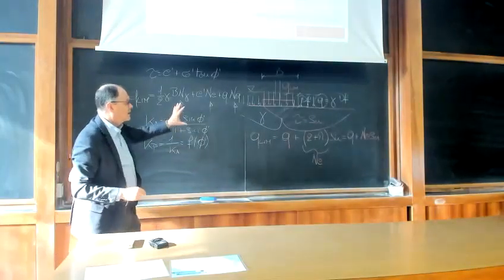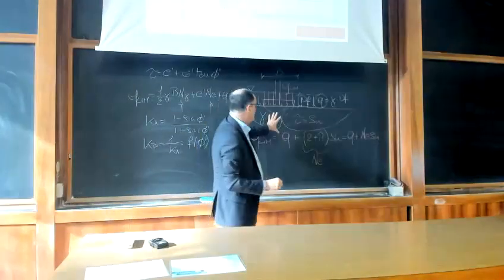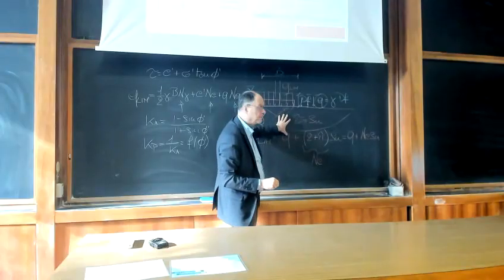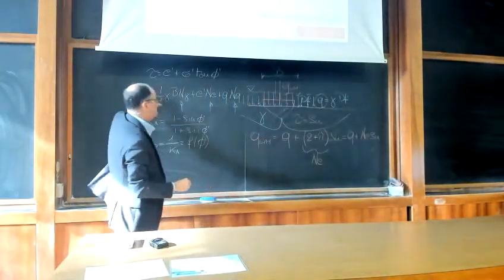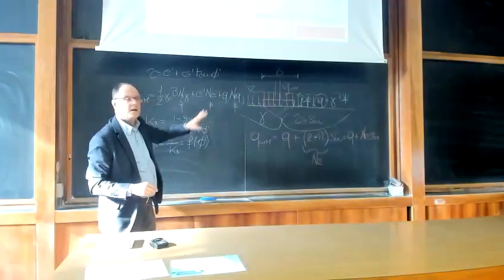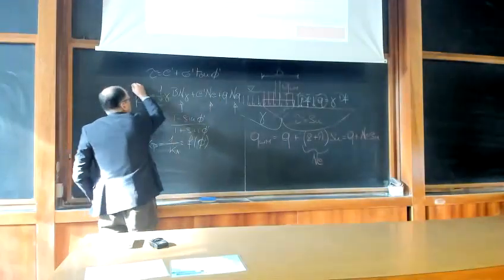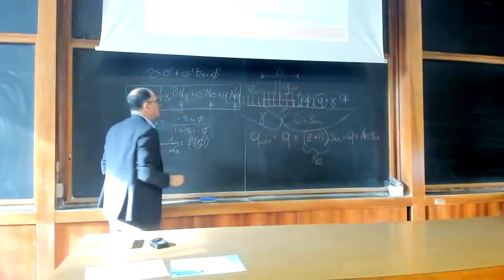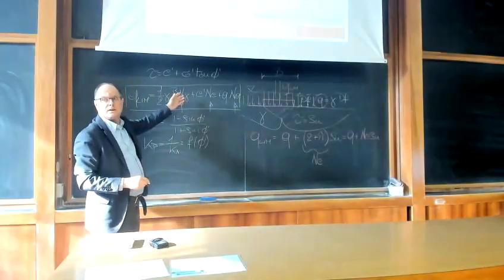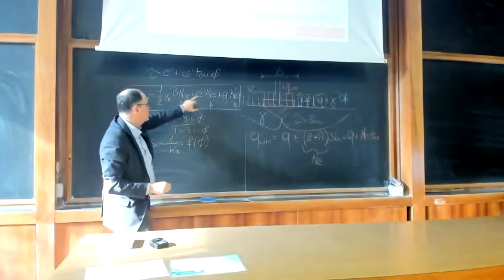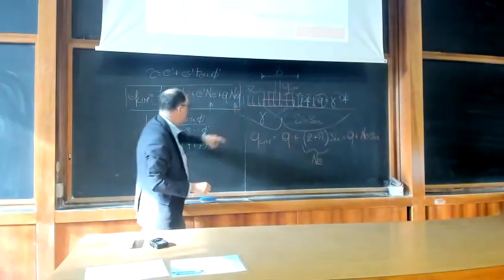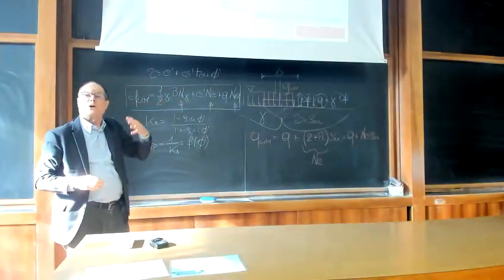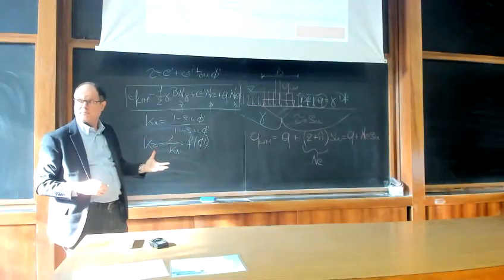And in fact, the most important parameter, which is the shear strength of the soil beneath your footing, does not appear explicitly in this expression. And this is, at first instance, a bit awkward. Where is the shear strength here? The shear strength is in all three bearing capacity factors, under these specific expressions or other expressions, which are always functions of phi anyway.